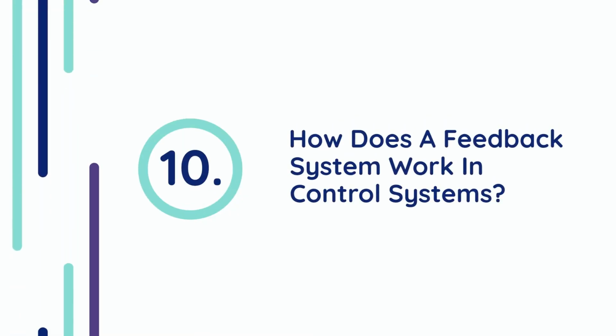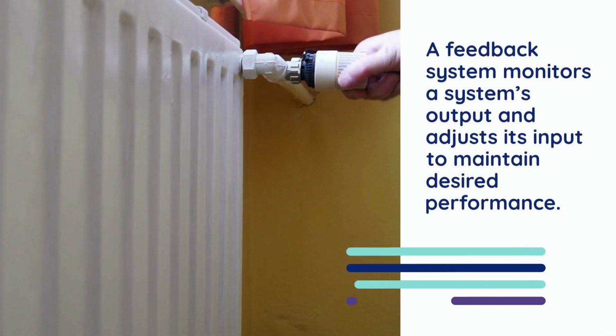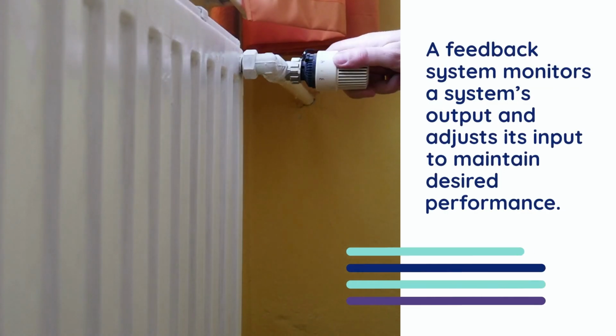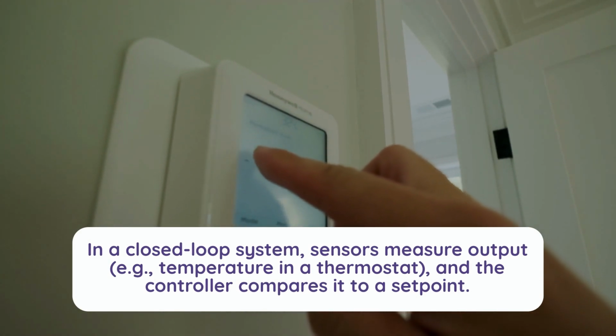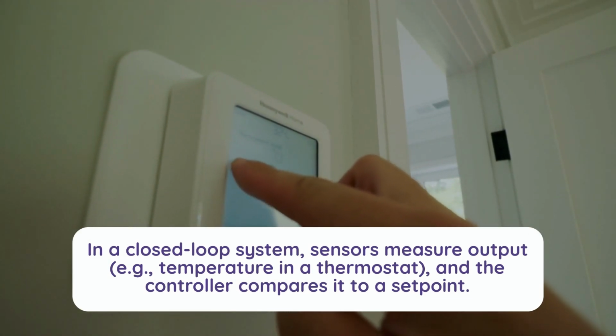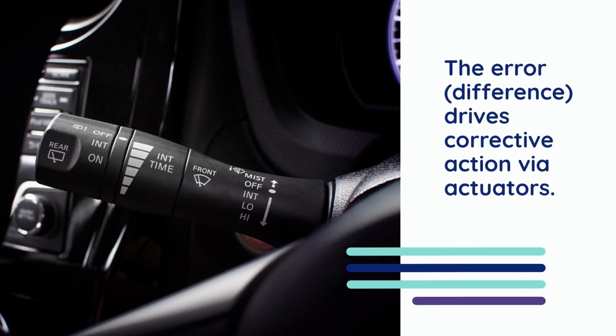10. How does a feedback system work in control systems? A feedback system monitors a system's output and adjusts its input to maintain desired performance. In a closed-loop system, sensors measure output, e.g., temperature in a thermostat, and the controller compares it to a set point. The error difference drives corrective action via actuators.